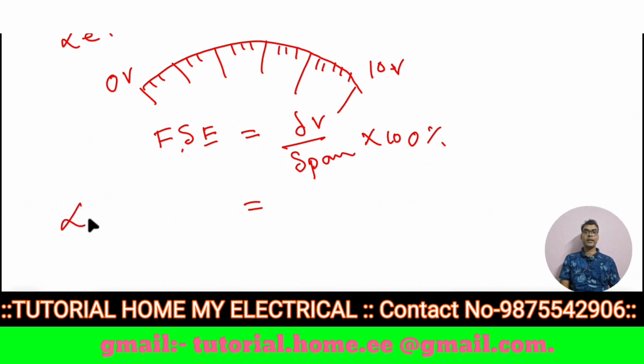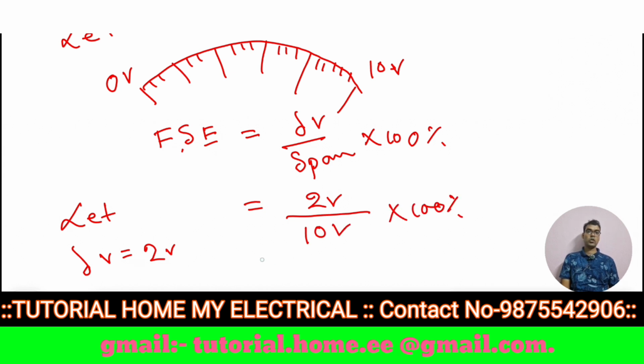We let the absolute error equal to 2 volt. Here we assume the absolute error is 2 volt. We may assume 10 volt, 5 volt, etc., but we have assumed 2 volt. So here 2 volt, span is 10 volt, into 100%, so 20%. Here the full scale error, with an assumed absolute error of 2 volt and span of 10 volt, is 20%.